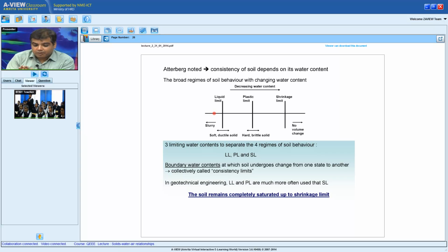If you go beyond this state, it still remains slurry. Probably the strength would be zero until it becomes like pure water. Remember, pure water has zero shear strength. So somewhere over here, it will just behave like water. So for a type of soil, the shear strength would be equal to 0, either it will be grainy or silty or clay.